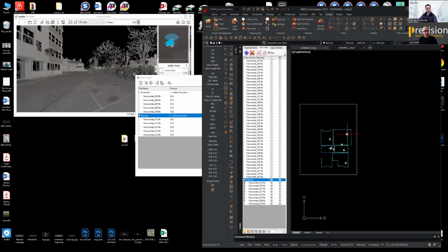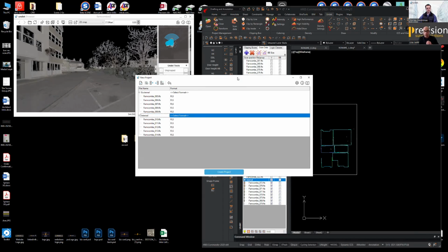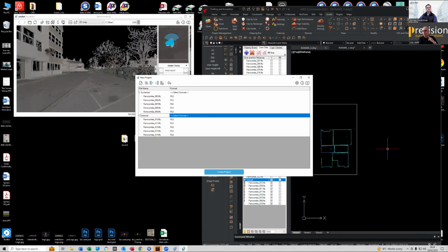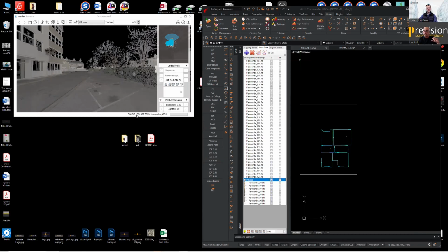You can, of course, turn on the bubble views. And these are the bubble views that come with your E57, your FLS data, to allow you to see that 360 data in your browser and stuff like that. So in terms of functionality, the indexer can then run away on its own. So if you are digitizing and you have another pool of data that you want to digitize ready, you can have this indexing in the background whilst you can still work onwards. So that's just a brief insight into what the indexer does. Once that's indexed, then of course you open it via the Undet plugin to digitize what you're after.